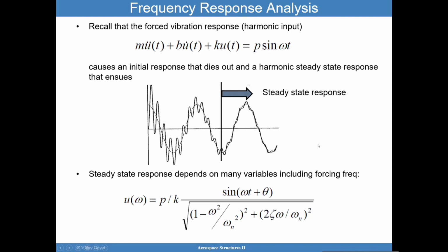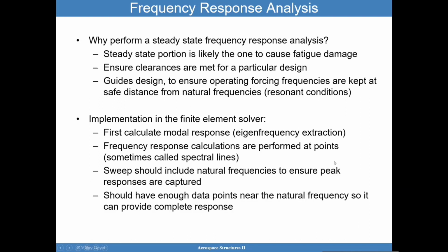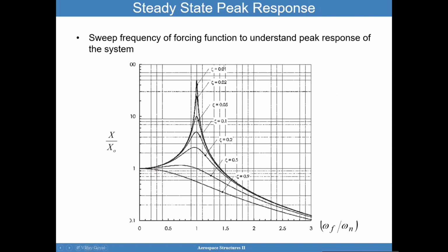And my point being here is you have to evaluate the fatigue damage due to these stresses oscillating. And so that's one reason why this is helpful. The second reason this is helpful is if you want to analyze to make sure the structure does not get into clearance problems. That's where this could be helpful. You can also use this analysis to design the system so you know what the peak response is, and then you can design around it.